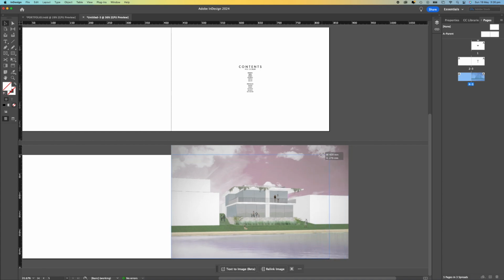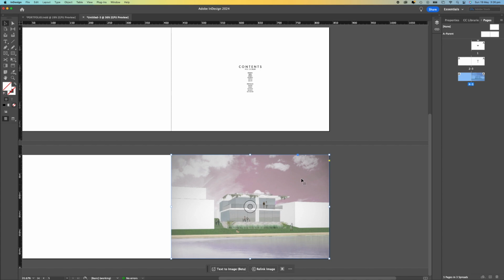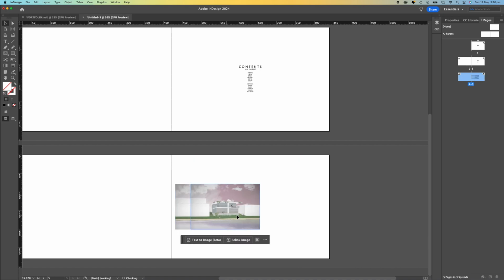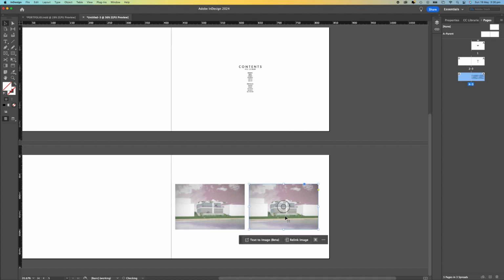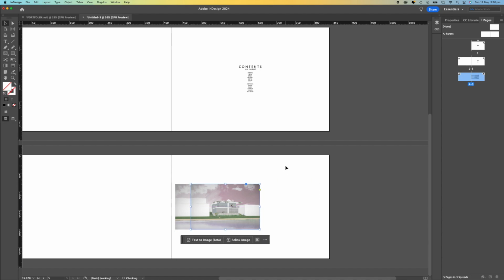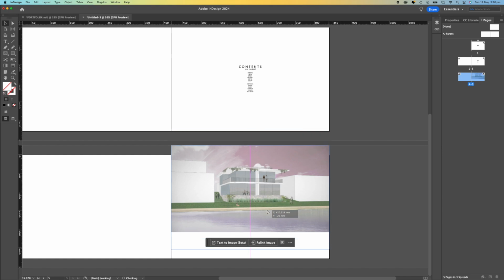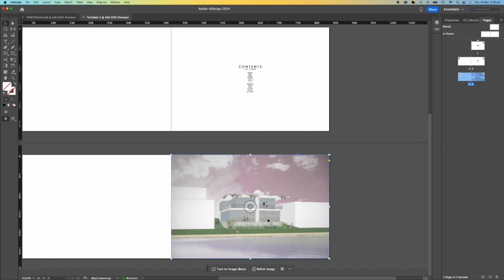A lot of the time we're going to want to resize it from the center. So for example, if we want to resize and make it smaller, keeping our frame edge coming in so that we can bring it in and make a copy, then have side by side or something like that, we can do that by holding Control Shift and then pressing Alt. That's going to bring it in with both the resize and frame edge. If we want to resize out, so I can have a full bleed image, it's Control Shift Alt for pulling outwards instead of inwards.